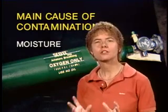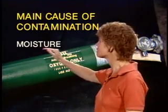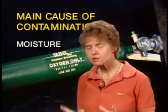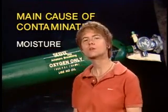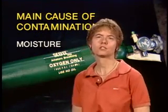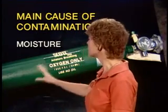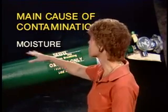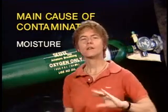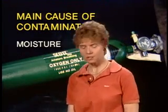The main cause of contamination in a gaseous oxygen system is moisture. Moisture can cause corrosion. Moisture in an aircraft oxygen system can also freeze at altitude and plug up the whole oxygen system. So you want to make sure that there's pressure maintained in the system, and that's why aviators breathing oxygen is moisture-free, unlike medical oxygen.